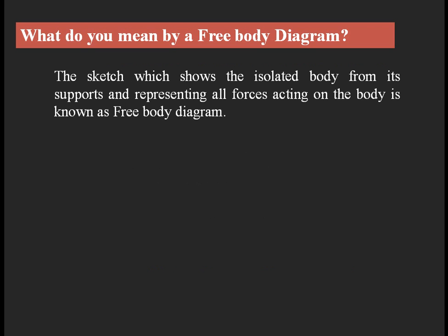So here, a free body diagram is a sketch which shows the body isolated from its supports and represents all the forces acting on the body. That means a sketch which represents the body separated from all its supporting elements and shows whatever forces act on that body due to those supporting elements. That sketch is known as a free body diagram.